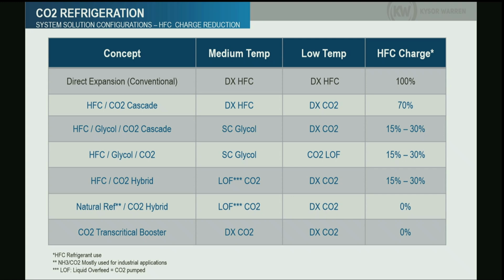So it's liquid going in, liquid coming out? Yes. Well, 100% liquid going in, about 50-50 coming out, because part of the CO2 evaporates in the display cases. With the glycol, you have 100% liquid coming in and liquid going out. With CO2, you have a mix coming back.